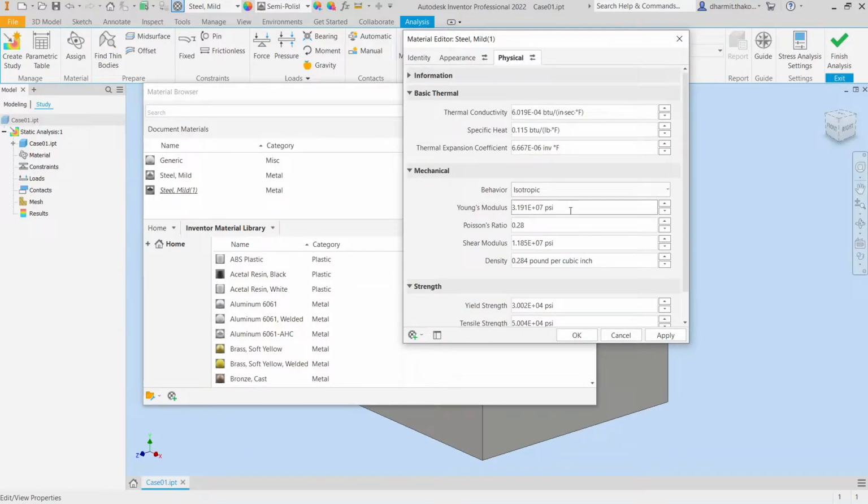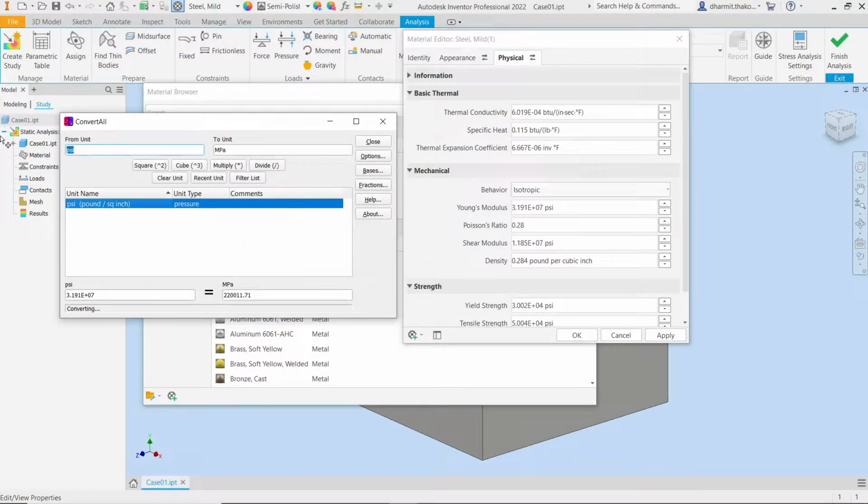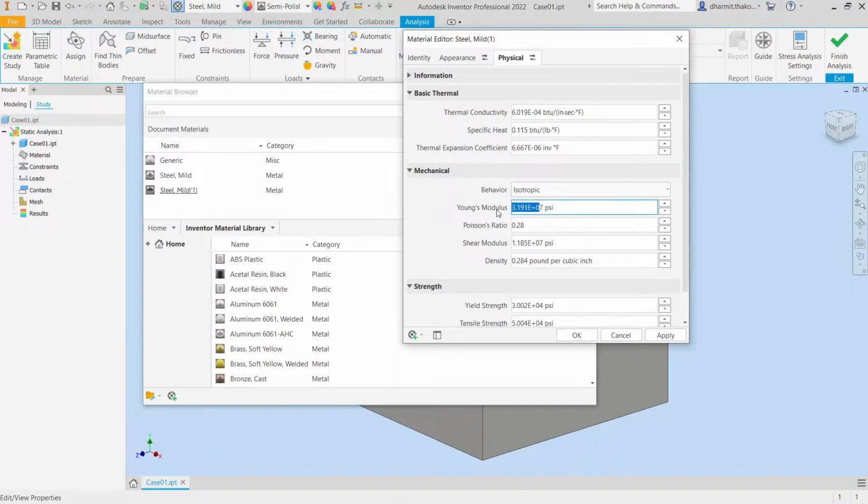Let's go in and add the properties that exactly what we want out of it. So now let's change from MPa to PSI, and we want that. So let's click this in the PSI values. And the only reason we are changing the Young's modulus and Poisson's ratio is for the fact that we want to keep everything the same for all of the other simulations.